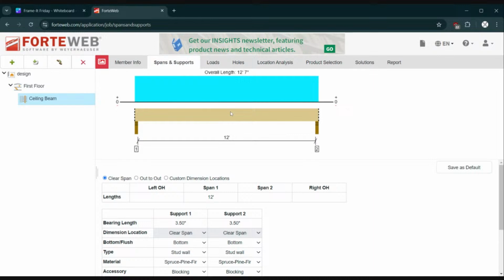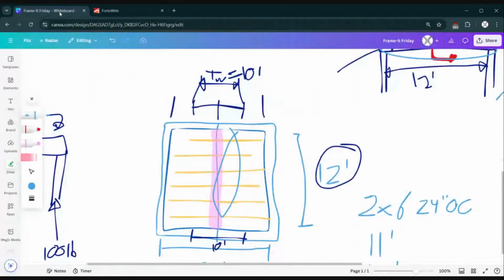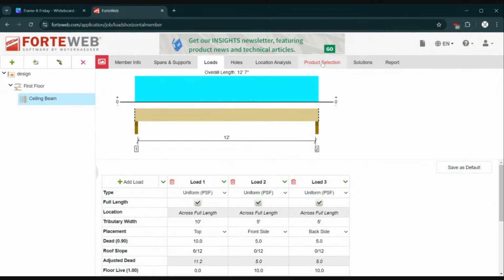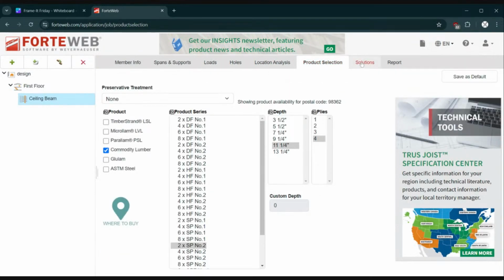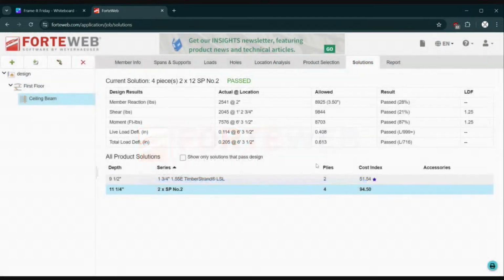And so in the center, if you load it with all of the loads from the house design that we just did here for super simple sake, and we use 4 2x12s, and we go back and check the math, it says our beam will deflect 0.2 inches. All right, that's pretty darn straight. The 2x12s themselves probably are not even toleranced to being 0.2 inches straight. So that's probably pretty darn good, okay?